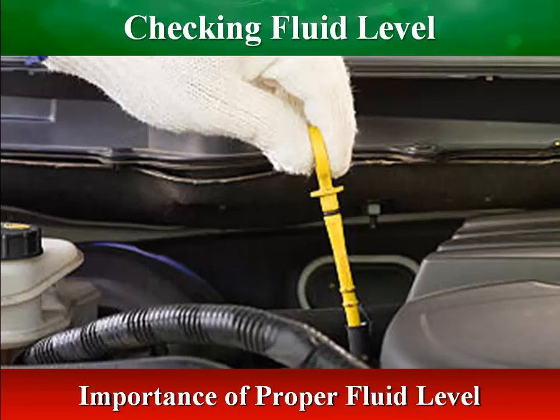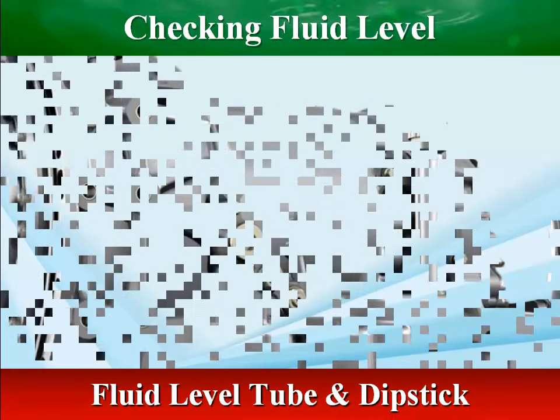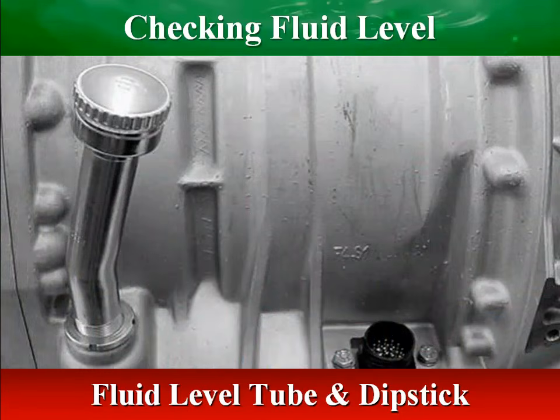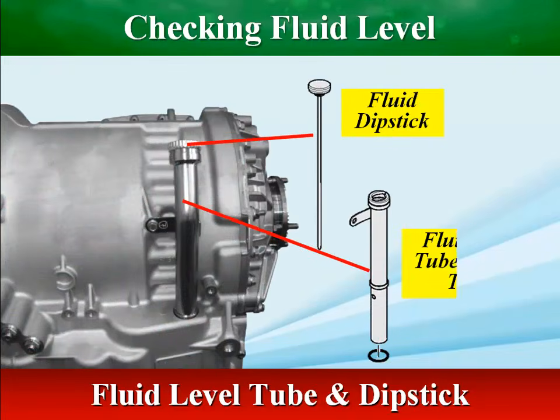It is important that proper fluid level be maintained at all times because the transmission fluid cools, lubricates, and transmits hydraulic power. If the fluid level is too low, the converter and clutches will not receive an adequate supply of fluid, which leads to transmission malfunctions and damage. If the level is too high, it causes overheating of the transmission, and fluid may be expelled through the breather or dipstick tube.